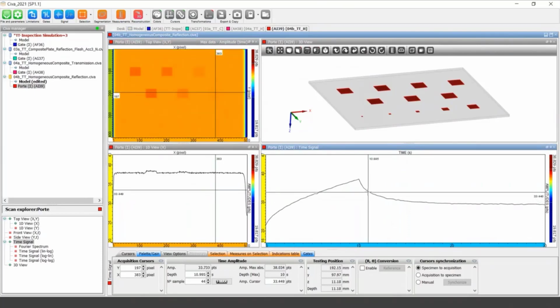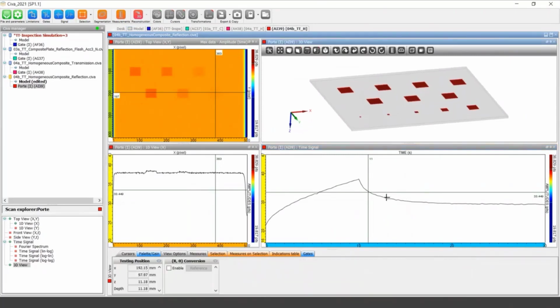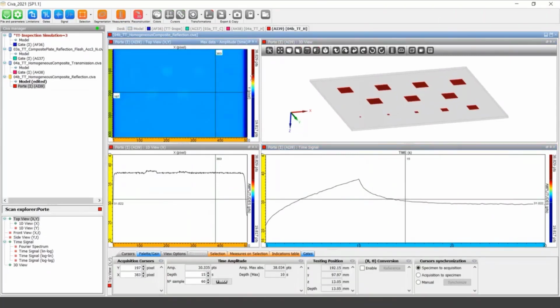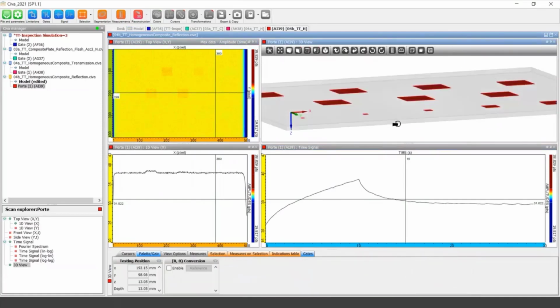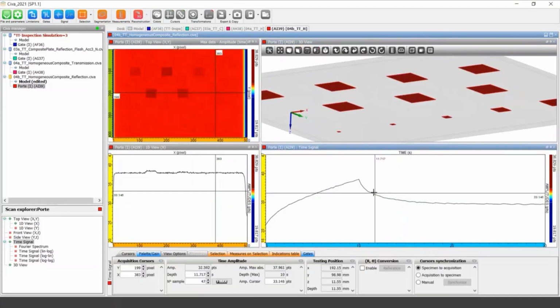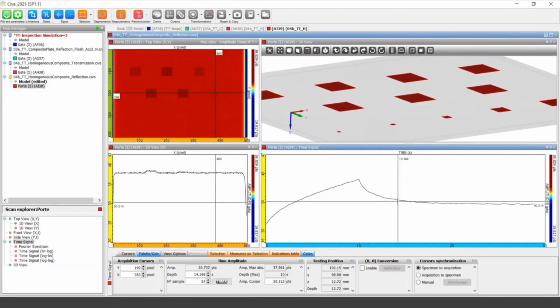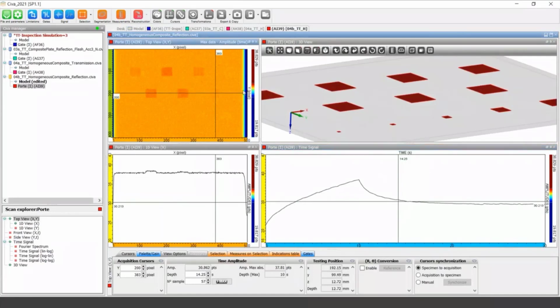So in this technique, the deepest one becomes difficult to detect, and you can see that I have nothing for the line with the smaller defects in this case. Due to the depth of the defect in reflection, I have less detection capability for the deepest defects.